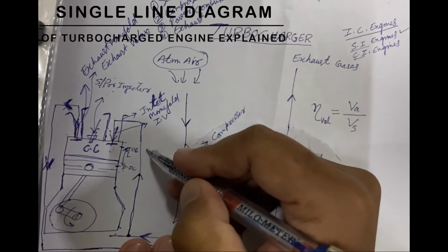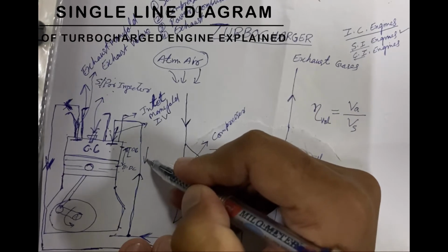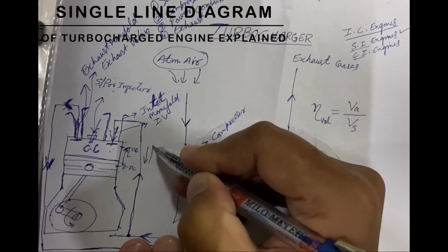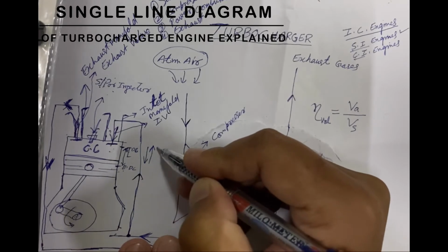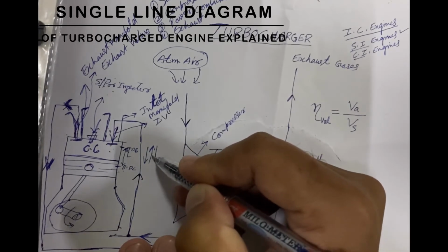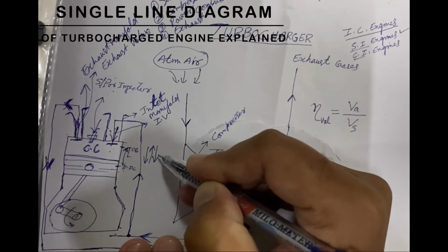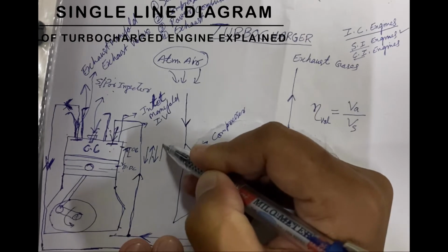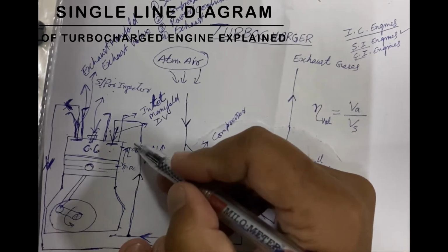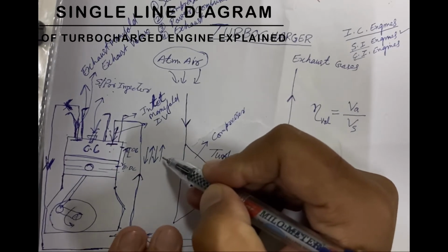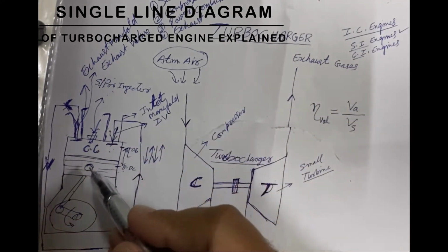Piston first of all comes down, this is suction, it goes back up from BDC to TDC. This is compression stroke. Then it expands by the combustion of gases. This is power stroke. Okay, then fourth stroke is when it comes back from BDC to TDC. This is known as exhaust stroke.